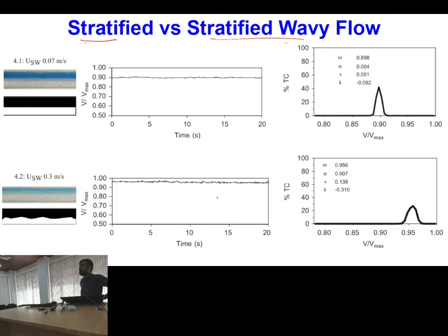That depends upon one's visualization power, so some significant outcomes should be there. Based on statistical analysis, you calculate the mean, standard deviation and kurtosis of this signal, and then the occurrence of the peak. Here you can see the peak frequency occurs corresponding to a signal of around 0.9, and the important point is that this peak has a significant magnitude.